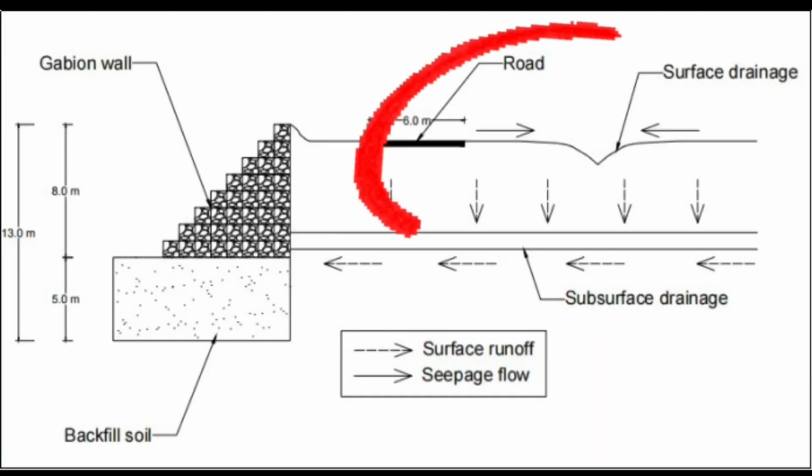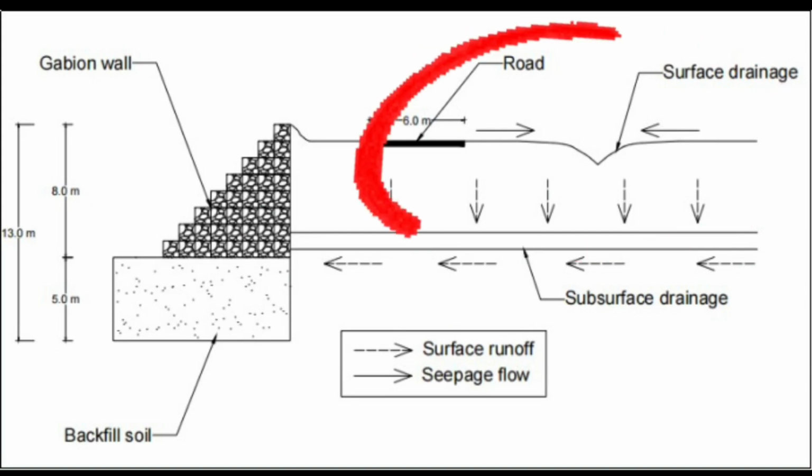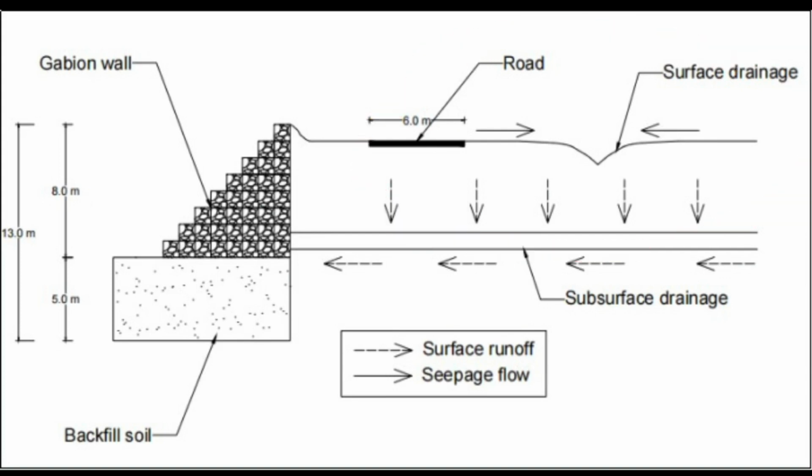Drainage system. As we can see in the figure, the process of removing water that has accumulated on the surface of the land is known as surface drainage. A surface drainage system should include land smoothing or grading and is made up of shallow ditches that run across the landscape. The rate at which water is removed from the surface by surface drainage is dependent on a number of interrelated factors, including the amount of precipitation, the characteristics of the soil, and the patterns of cropping if there